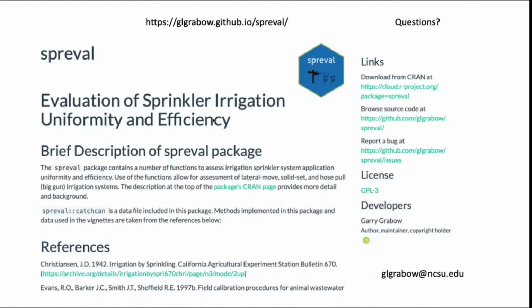Yes. My experience comes from more agricultural applications, but there are an array of filters. You can get screen filters that are used a lot with groundwater if you have a sandy stratum you're pumping from.